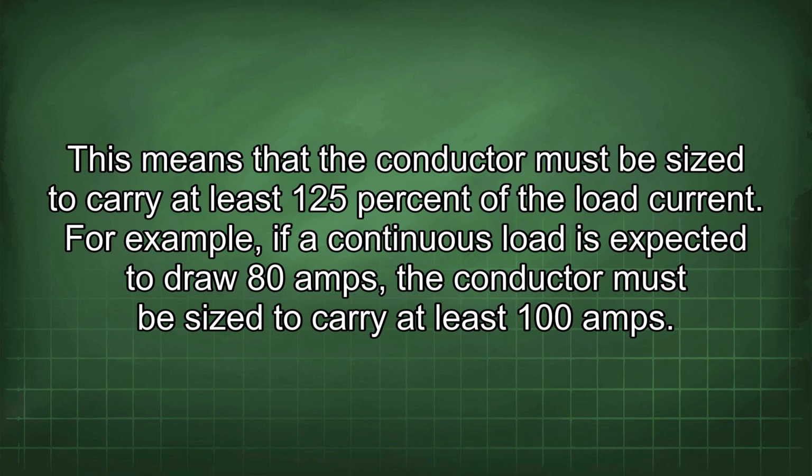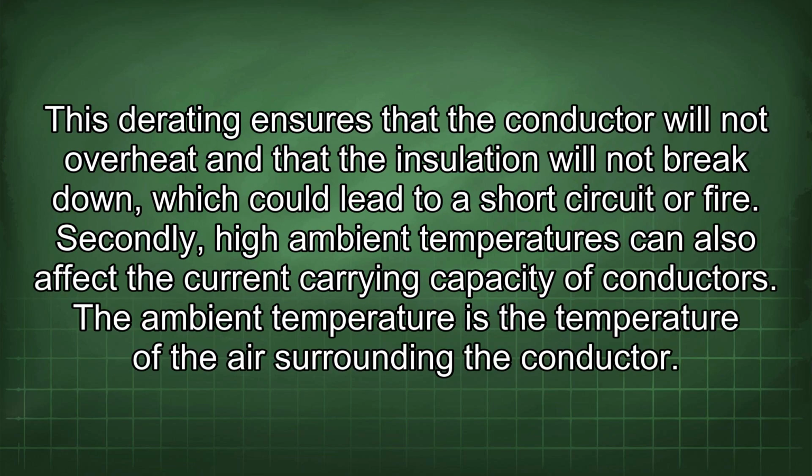For example, if a continuous load is expected to draw 80 amps, the conductor must be sized to carry at least 100 amps. This derating ensures that the conductor will not overheat and that the insulation will not break down, which could lead to a short circuit or fire.